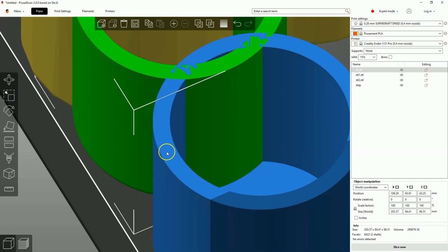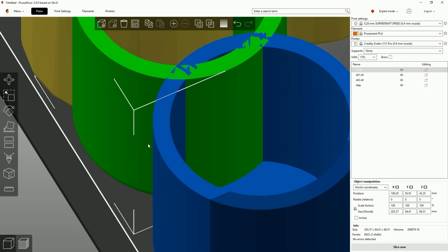More and more slicers, in which we prepare programs for 3D printers, support STEP files. So, if you have the opportunity, I think preparing programs for 3D printers based on STEP files will be a better solution. As for the STEP format, it is also widely used in CAD/CAM systems. It is a universal data exchange format between CAD/CAM systems, and we can use such a file in another program.